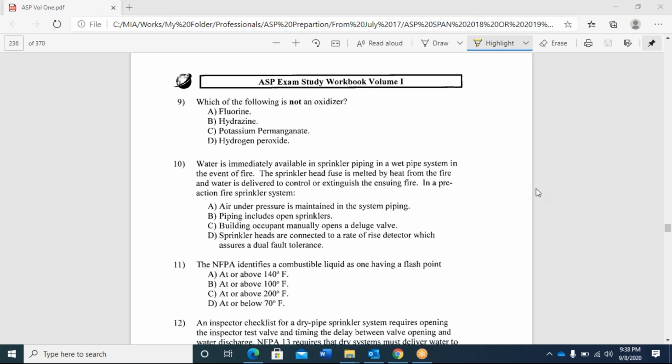Okay, that is the jockey pump. That jockey pump will always maintain the pressure inside the piping system. Once the sprinklers open by the heat detection, there is one fuse, and when it melts, it will give you the water.